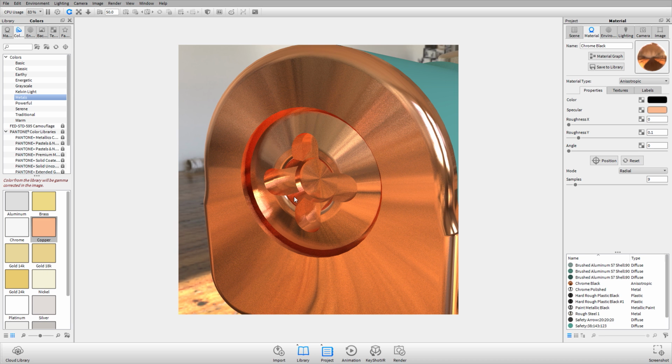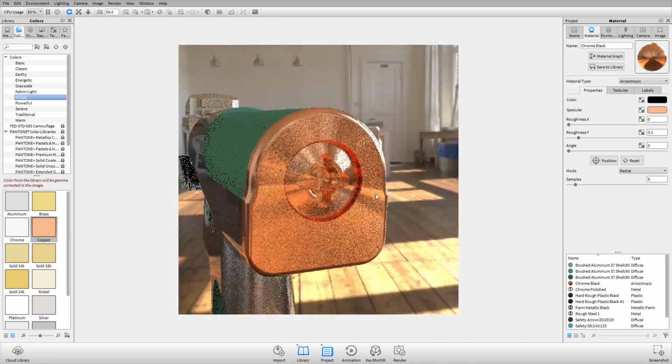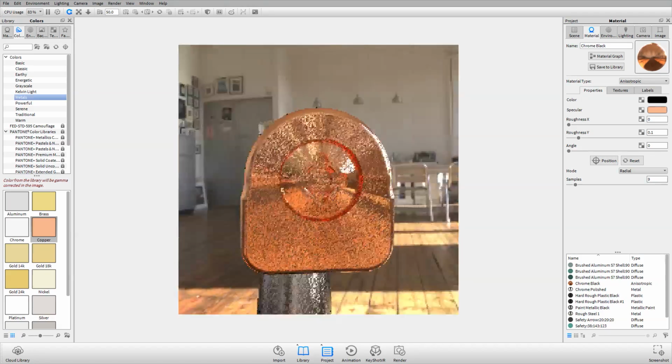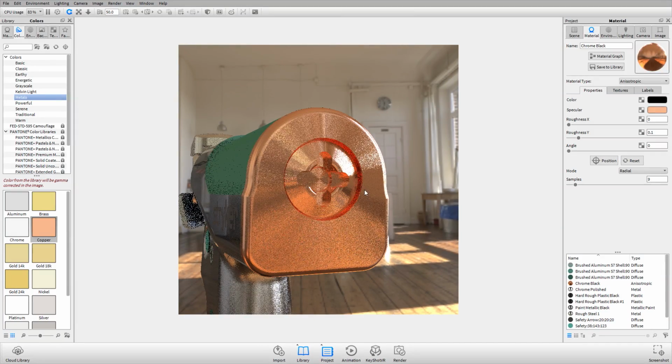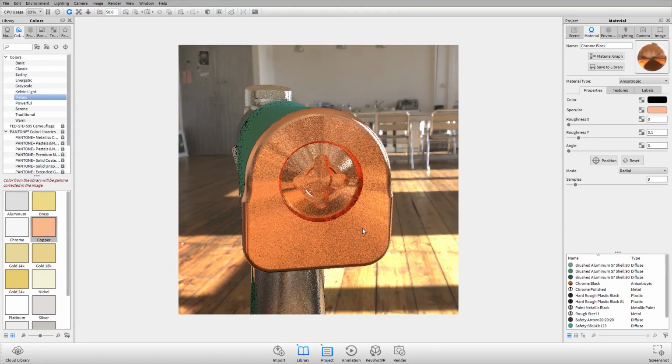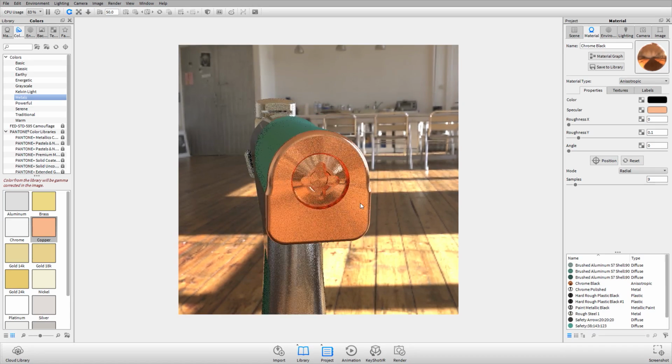And bear in mind, for the anisotropic material, we still have yet to texture it. We haven't touched the brush textures on this at all yet. What we're saying is, on a material level, this is how light is handled. We're determining it using our roughness and our mode. So pretty big deal if you've messed with kind of brushed metals or been frustrated trying to get that result. So again, still no textures on it, but we're getting a nice, strong radial reflection on that material itself.